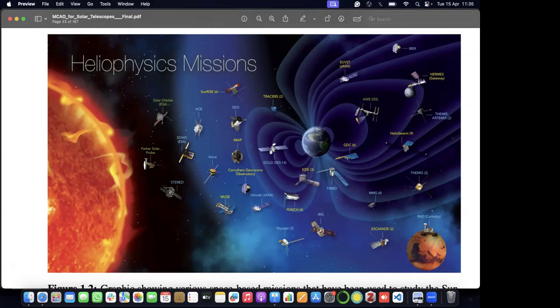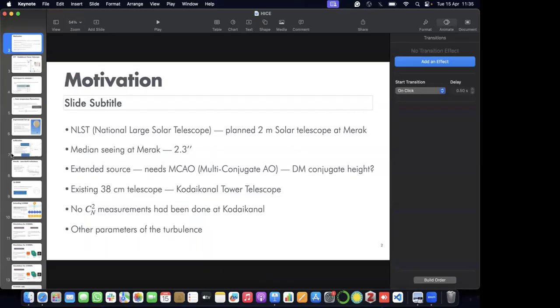DKIST is a 4-meter telescope, and a good friend of mine is the control engineer there. One of the biggest problems is when the primary feeds into the secondary, and the secondary is small. Thinking about the amount of heat going into the secondary, one of the biggest engineering challenges of the telescope is not melting M2, and getting the heat out of it. Which is why we have a 36-meter focal length, about 120 feet, so it's a long tunnel that you go inside.